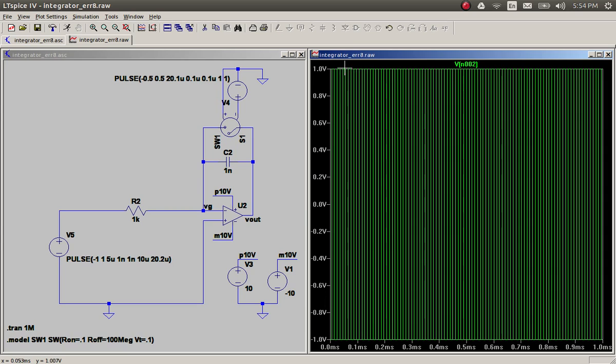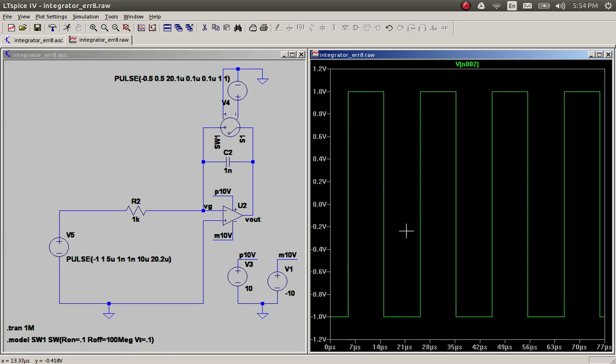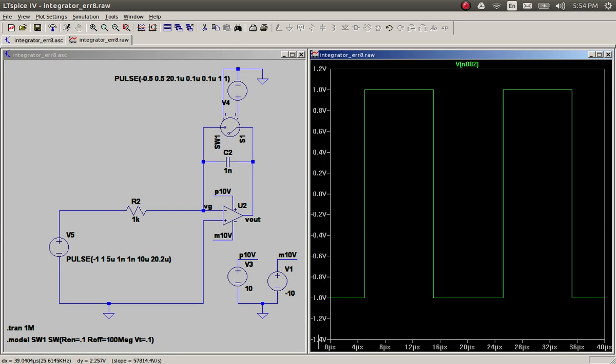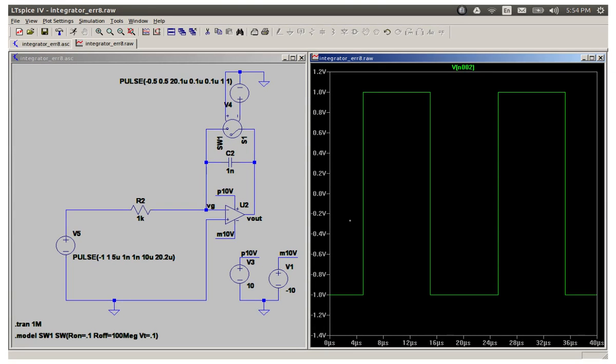And why is it that we have a small DC component? And I'm sure you figured that out by now. It's because something's wrong with an input statement. So let's see what this statement is saying. Ouch. So we have a -1, check, that's okay, to +1, that's also okay, 5 microsecond on time, that's this one,